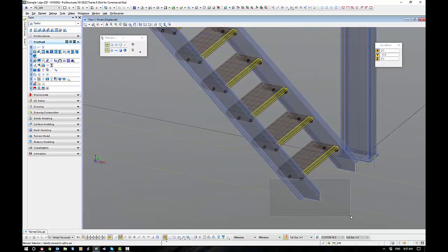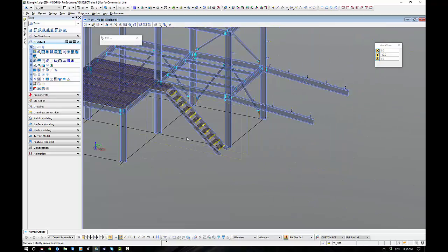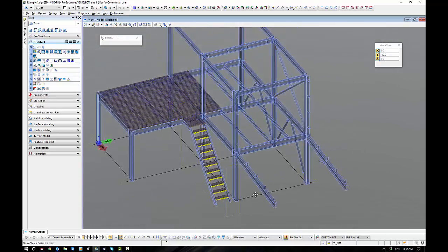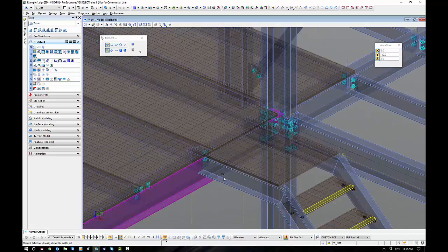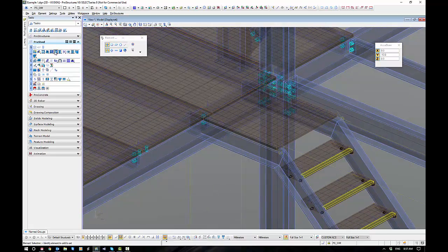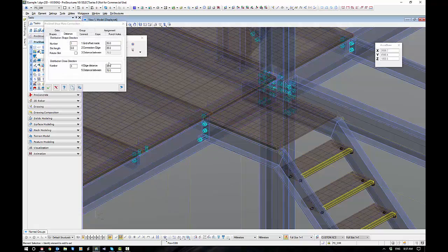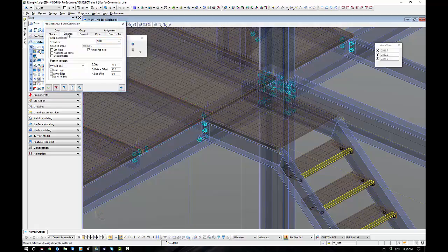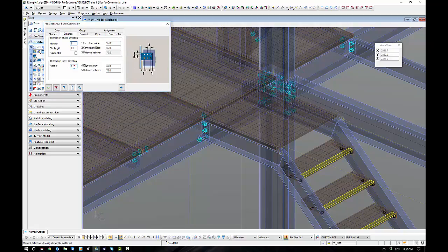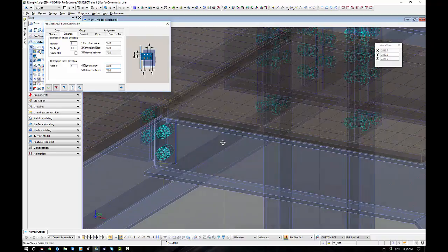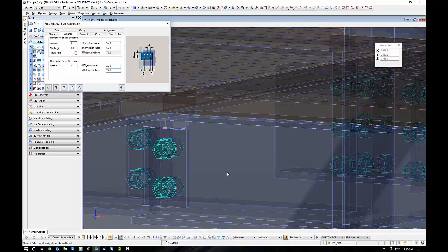Next thing, we'll muck around with this connection. You could do your base plates as well using the base plate command if you wanted to, with an offset. Nice and simple. Okay, I won't worry about that in this session though. Okay, so let's get a shear plate connection in here. Supported to supporting. That's currently set to the last thing we connected up, which was 3 bolts. So let's go to distance and set that back to distribution, back to 2. Okay, and you'll see that it'll live update.